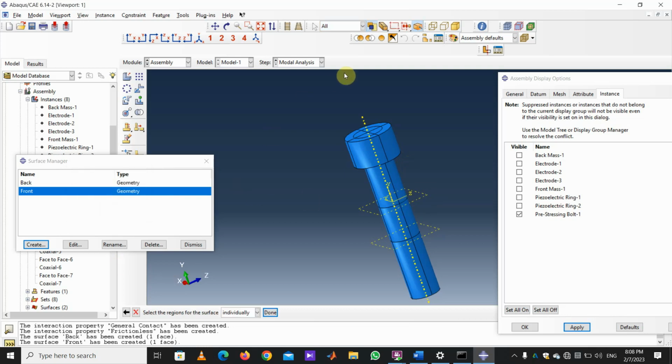For selecting correctly here, I select the selection type that selects from just exterior surfaces, so that if there is an internal surface in the bolt, by picking this mode, those internal surfaces will not be selected.